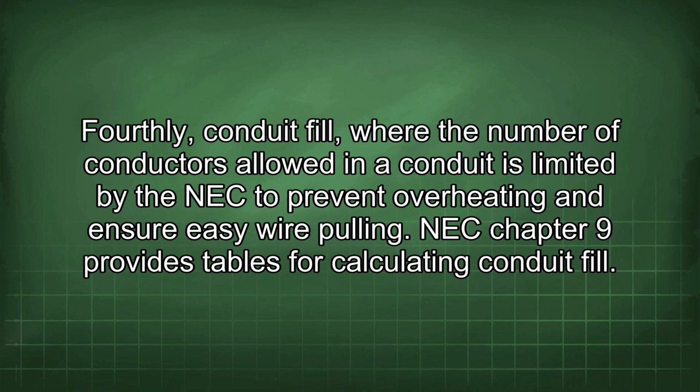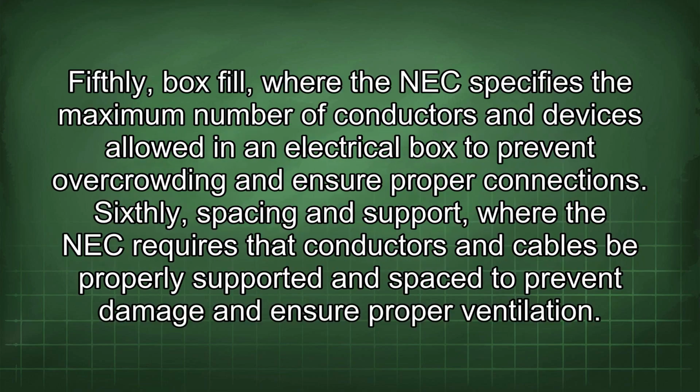Fourthly, conduit fill, where the number of conductors allowed in a conduit is limited by the NEC to prevent overheating and ensure easy wire pulling. NEC Chapter 9 provides tables for calculating conduit fill. Fifthly, box fill, where the NEC specifies the maximum number of conductors and devices allowed in an electrical box to prevent overcrowding and ensure proper connections.